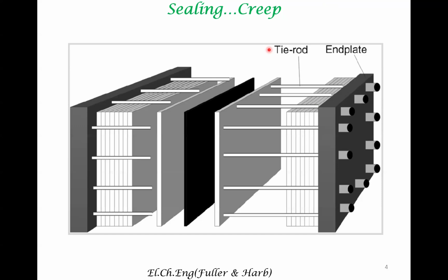This feature is called creep, and what is known is that the creep deformation is enhanced with increase in temperature. If the temperature is more, the susceptibility of the material to creep is also greater. Therefore, the issue of creep in SOFC is greater because the temperature of operation is fairly high.